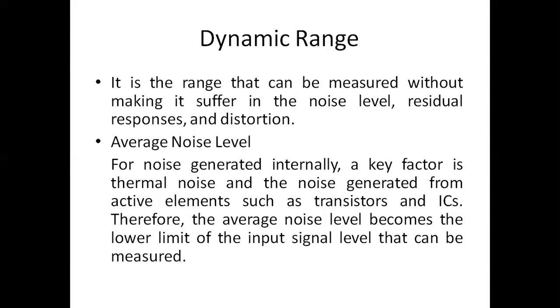So average noise level is the thermal noise and the other noise generated from the active elements like transistors and ICs. So this average noise level must be below the lower limit of the input signal level. Otherwise, if this average noise exceeds the input signal level, the signal can't be measured.